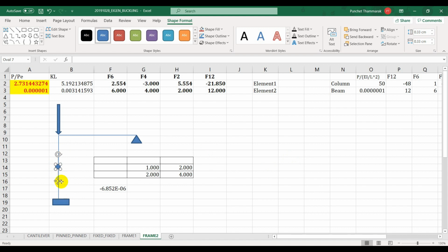It doesn't really have to be right at the middle because the maximum deflection might not be exactly at the middle, but if you put the degree of freedom in that vicinity, you can at least pick up the effect. Not absolute max displacement point, still fine, but you are close to that point, you will get the influence, the contribution from the large deformation and large P delta at that area.